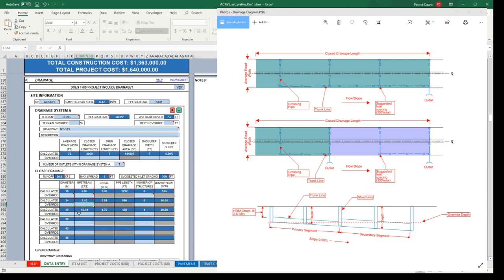So if you had a branch coming in halfway through this network at the 24-inch pipe segment, let's say if it was 2 CFS in addition, you have to add that manually in your head, so if you had 2, that would make it 9.45 would be an override. So it's not an addition, it's overriding it completely.